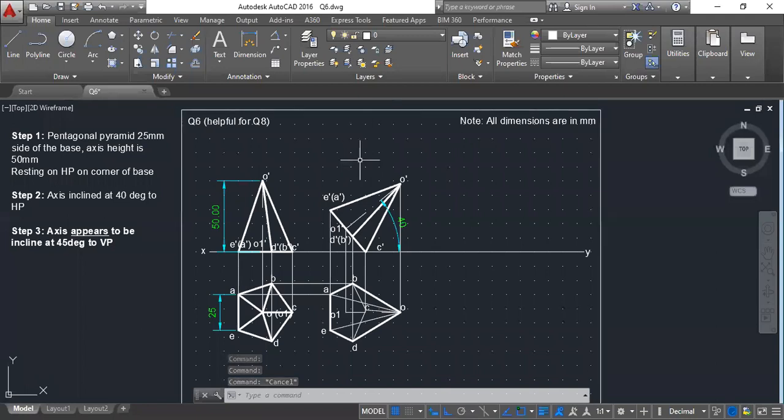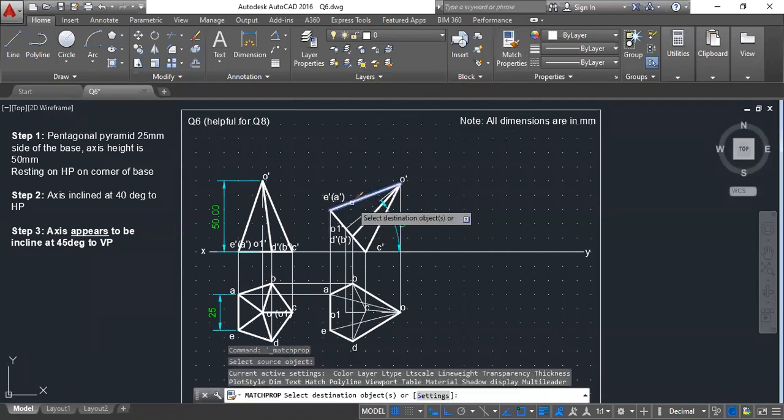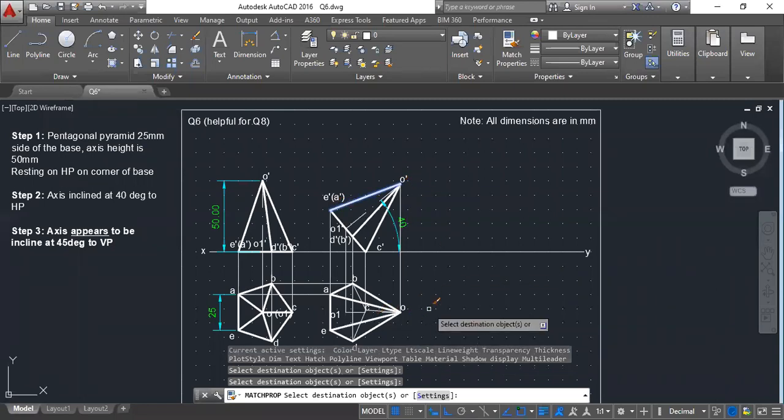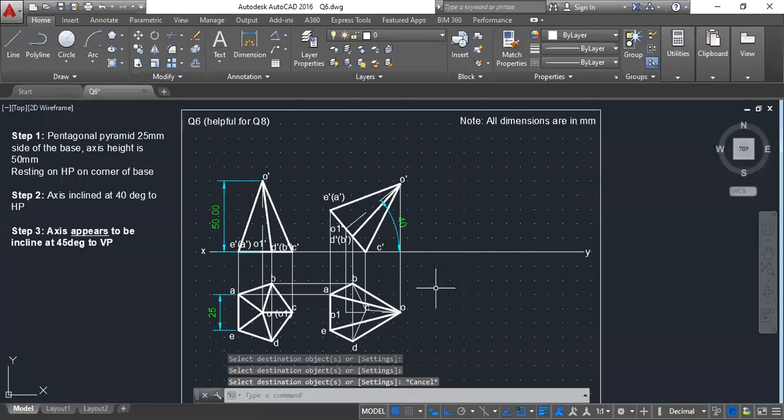So when you are seeing something from the top, can I see the line OA? Yes, I can see it when I'm seeing it from the top. So I'll make it dark. Okay, I'm making it dark. Can I see the line OE from the top? Yes, I can see it, because that's the topmost line that can be visible. So I'll draw that. Next question comes here.